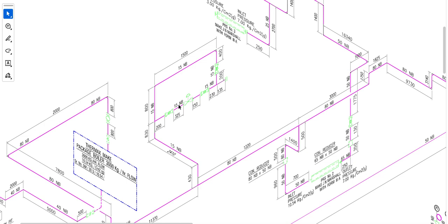We have the pressure reducing station, and that is used for the low pressure steam application. As this is below 3.5 bar gauge, there is no requirement for IBR regulations to be followed. Our line goes to the next PRV station.